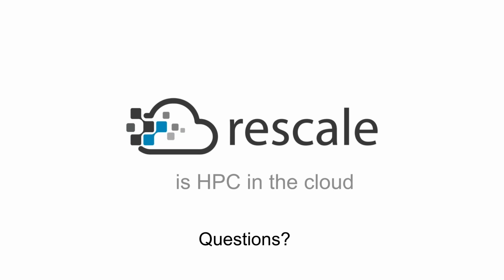We do allow the user to specify parts of the mesh if they choose. If you have a specific mesh shape that you want to run, you can include that in your surface and set that up in Studio. It will allow you to put a specific type of mesh where you're having some spray, or around to capture some boundary layer effects and things like that. That's called inlaid meshing. And of course, you can look at our documentation for more information on that.